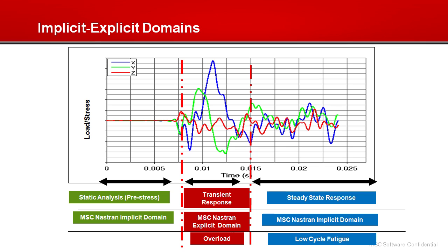This stage can be best modeled by an implicit solver. The objective here is to compute the stress and the deformations of the blade because of the high rotational velocities prior to the fan blade out and transient response in the second stage.